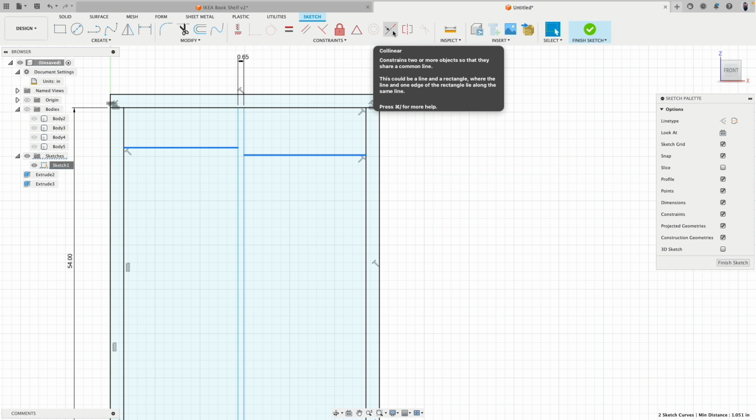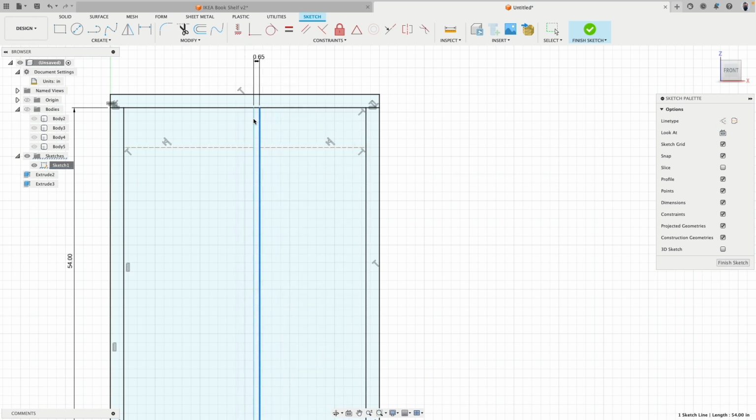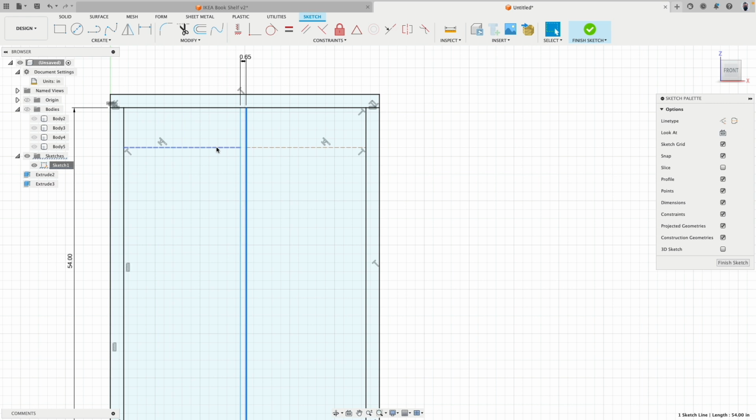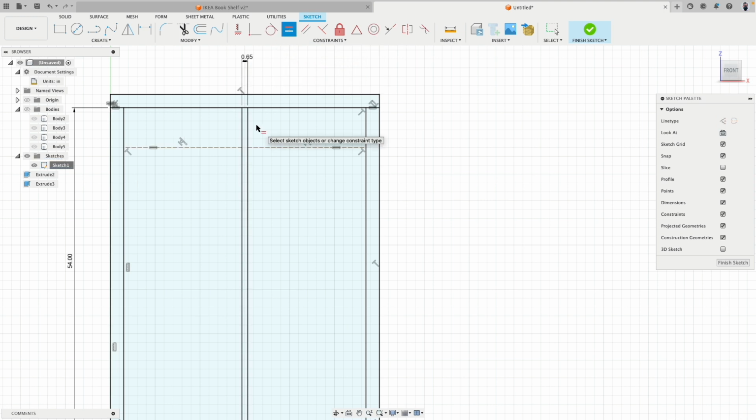Okay, how does this look? Click it. They're really on the same ray. Perfect. These 2 lines, I don't want to be modeling anything, so I can turn them into a construction line. You see they're dashed. When I move this line, you see this adjusts the length of this 2. So this means, hey, if I actually make these 2 lines equal, doesn't that center the rest? And voila, it does, perfectly centered.